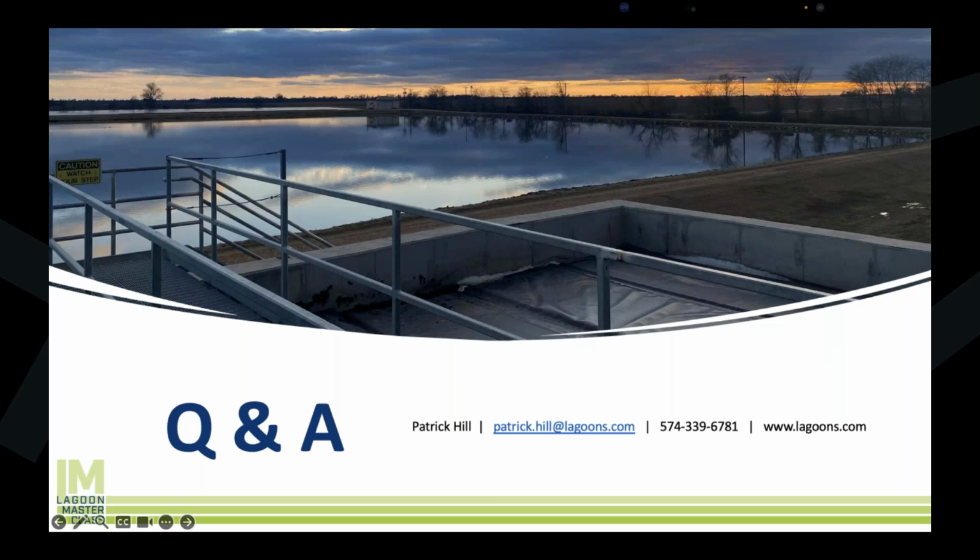We did a whole webinar on nitrification, which I encourage you to watch, but you really need a specific nitrification reactor that's designed to nitrify in cold weather. Our Nitrox system is one of those, but there are other systems on the market as well that you can literally bolt onto the back of your plant. And unfortunately, that's just it. You need to convert the ammonia into nitrate to stop the toxicity.